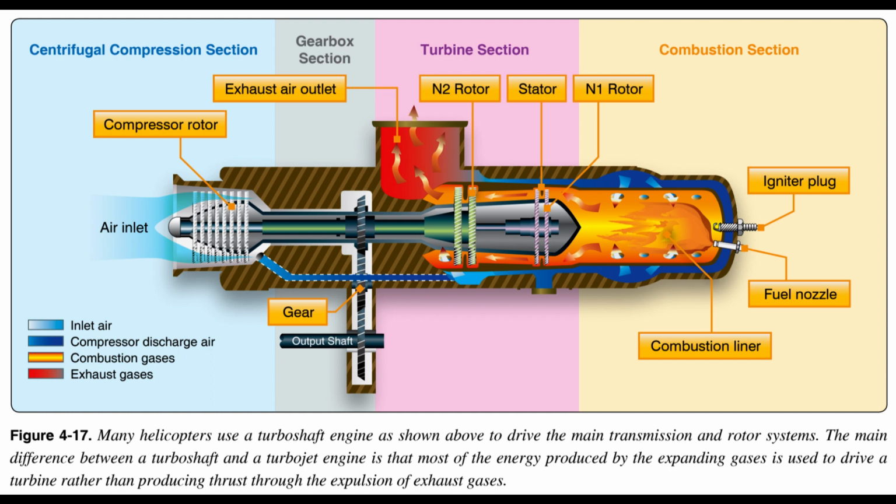Power is provided to the main rotor and tail rotor systems through the freewheeling unit, which is attached to the accessory gearbox power output gear shaft. The combustion gas is finally expelled through an exhaust outlet. The temperature of gas is measured at different locations and is referenced differently by each manufacturer. Some common terms are interturbine temperature, ITT, exhaust gas temperature, EGT, measured gas temperature, MGT, or turbine outlet temperature, TOT. TOT is used throughout this discussion for simplicity. Figure 4-17. End of page 4 to 9.